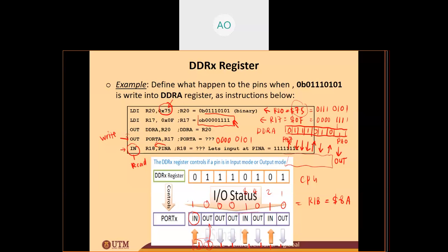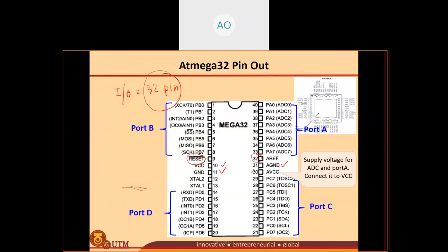Port A and pin A are the same code, different. Okay, if you're going to read, we need to read from pin A by using the in instruction. If you're going to send out the data, we send out the data by using the out instruction, but using the port A. But it comes from the same pin, it will come from the same pin here.